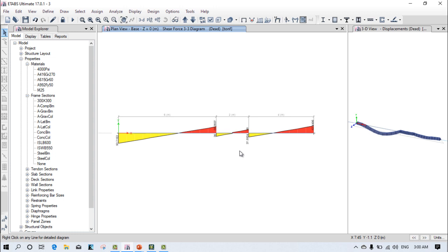So this particular pattern is generated, so it is very important to neglect this particular loading condition. For that we need to assign the proper dimension of the beam. You cannot change the loading conditions you apply, but you need to apply the change in the volume, or change the mix design of concrete. Or during the analysis, if you have that much amount of shear forces, you can change the reinforcement. That reinforcement will carry this particular kind of tension.